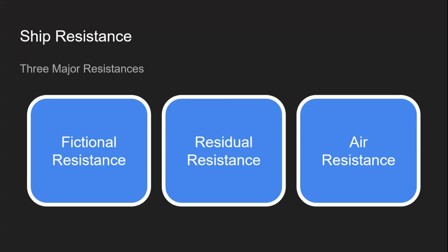So we didn't cover this in the presentation, but when it comes to ship resistance, the major thing is water resistance: the residual resistance and frictional resistance, and air resistance. Air resistance is the case when the upper part of the ship is in contact with the air fluid. So we basically covered these three. And for discussion, I would like to discuss the red part.